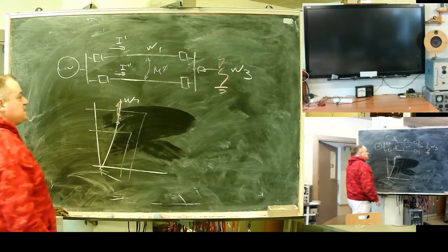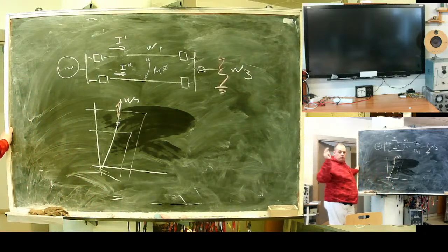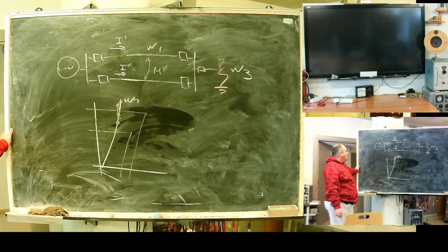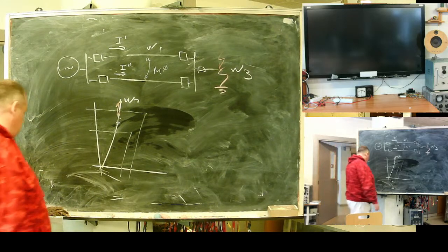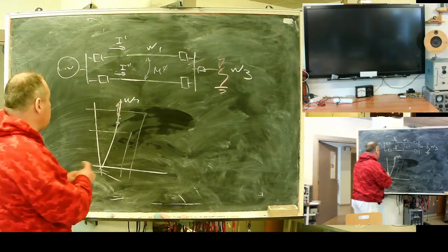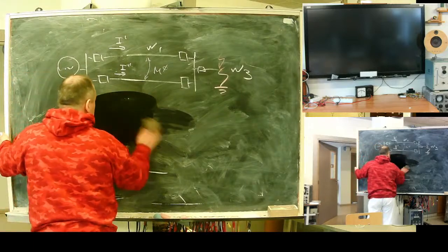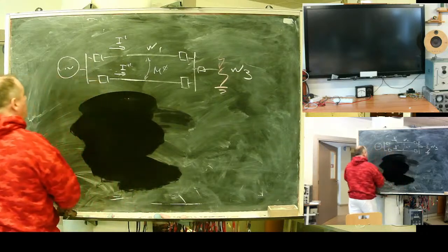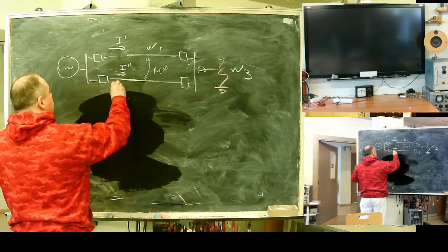So resistance increases, fault moves outside. Also may cause delay in backup operation. But this is not a disaster. Actually, modern protection terminals offer one interesting thing.